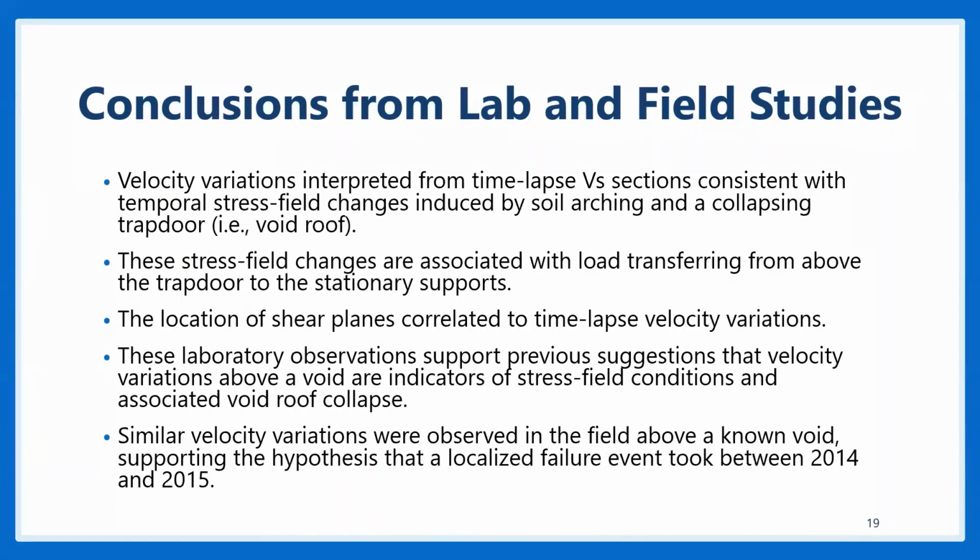So in conclusion, we observed velocity variations in the time-lapse shear-wave velocity sections, both in the trapdoor or the physical model I showed you, and we believe these changes in velocity are associated with a load transfer phenomenon above the trapdoor.